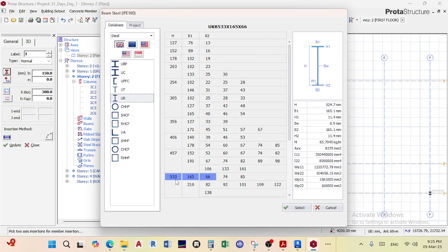And also, most importantly, here we have very long spans. This is like a general rule of thumb, because the longest span is about 11.7, right? And so you do not want a thin beam, because of deflection. It will bend according to the WL squared over 8 formula, or the QL squared over 8.